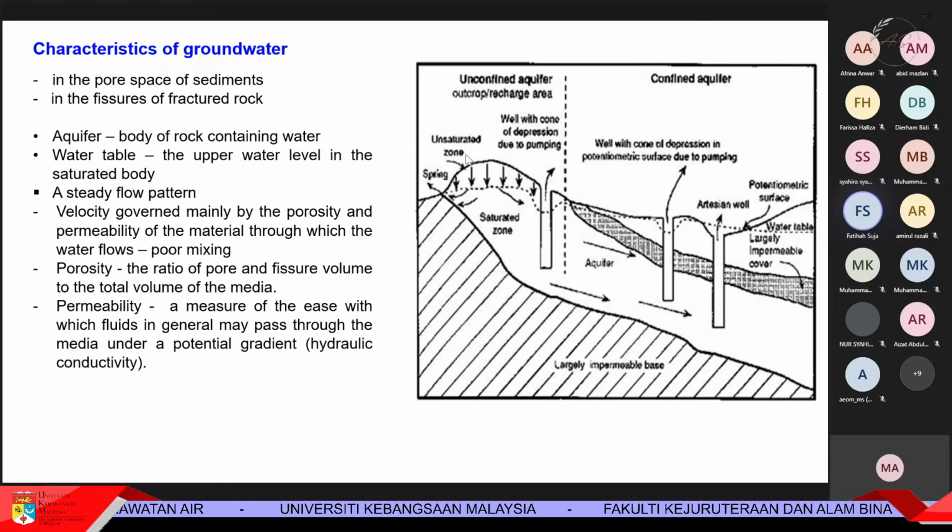So actually the risk of contamination will depend on the depth of the overlying unsaturated layer, so how big the unsaturated zone is, the rate of infiltration to the water table, and the land use in areas surrounding the sources here. Okay. So if you take groundwater, you also have to look at the location, whether it is a confined aquifer or an unconfined aquifer, if your source is from groundwater.